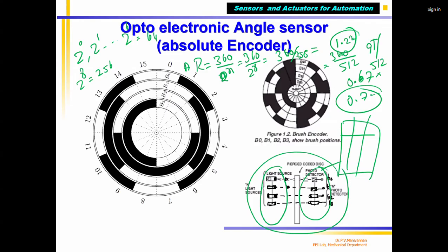So you will see this wherever you want to measure, for example a CNC machine, because a CNC machine can rotate through an angle, correct? You want cutting tools, drilling, or the motor angle to be measured, you use an absolute encoder. If you want to measure speed, you won't use an absolute encoder. Absolute encoder is generally used for angle measurement, no doubt, correct? Accurately, and it is expensive.